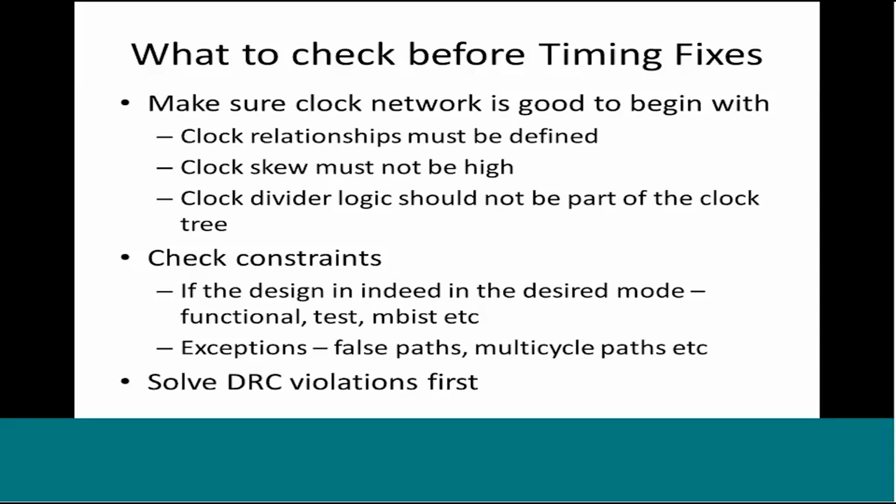It can be any other company. This tool can be Magma, this tool can be Cadence Encounter, anything else, or it can be Synopsys ICC. So these backend tools are geared towards implementing the design from the netlist stage. So the input to them is the netlist, the output is again the post layout netlist and the parasitic data.